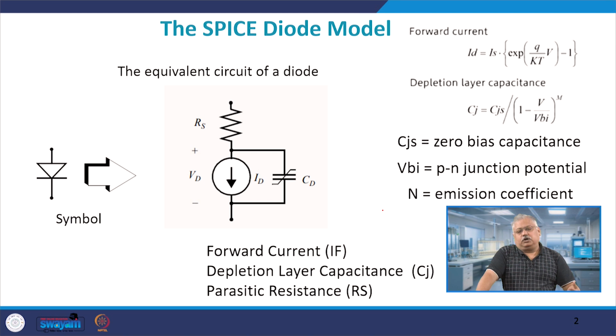So, just to recapitulate what we did in the previous lecture, we looked into a diode, and the diode was looked into as a switch, because on forward bias the current was relatively large, and on reverse bias, before the breakdown, the current was relatively small. So, you can use a diode as a basic switch as well.